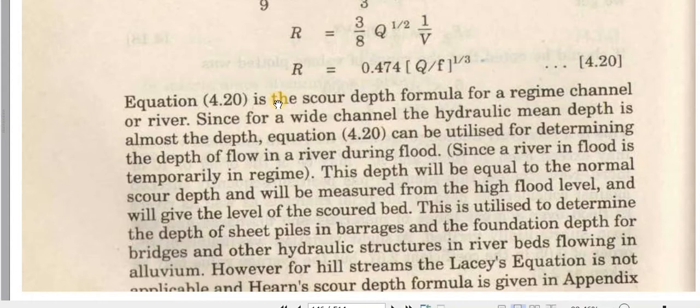Depth of flow is one term, and scour depth is another term. For example, if the depth of flow is 5 feet and for scour depth R we get 8 feet, then we can say that the lower 3 feet, from the channel bed down below the bed, can be eroded. So R is the maximum scour depth, that is, the maximum scouring at the bed, how much depth this scouring can reach.